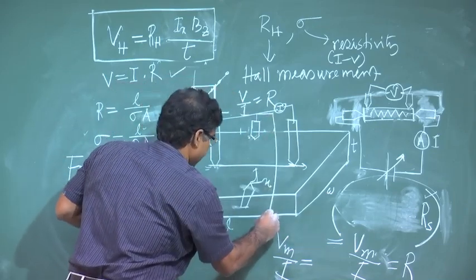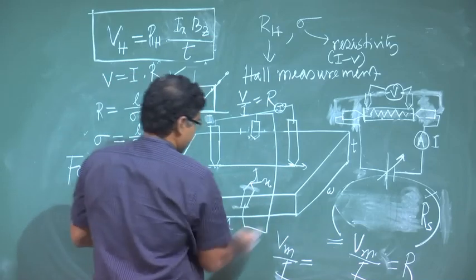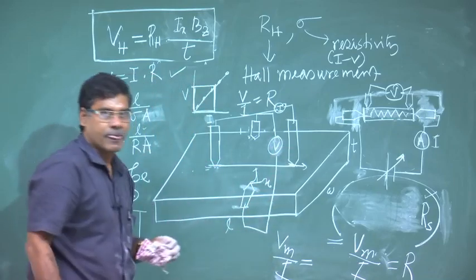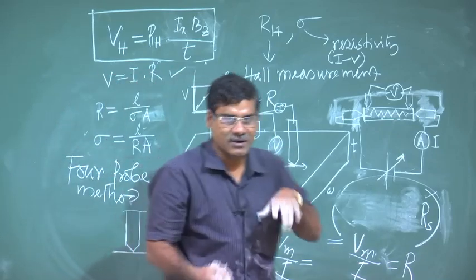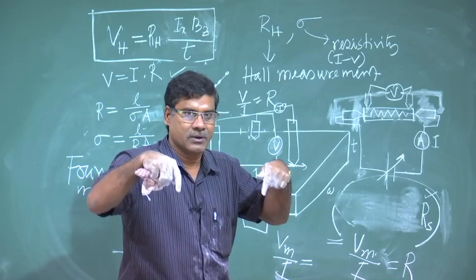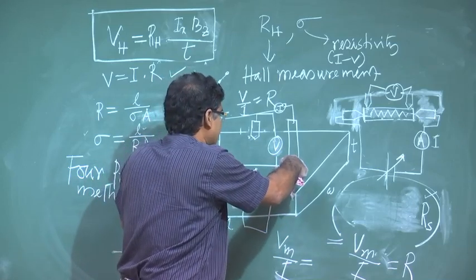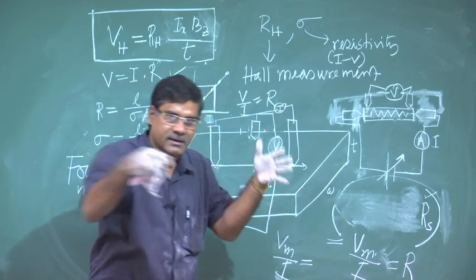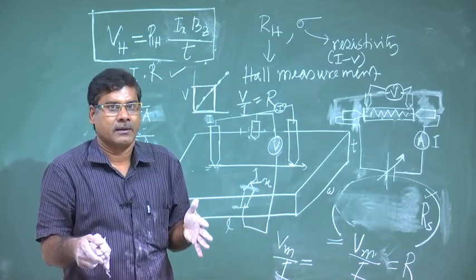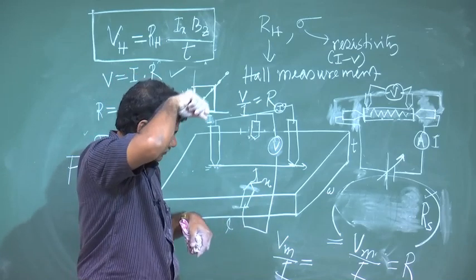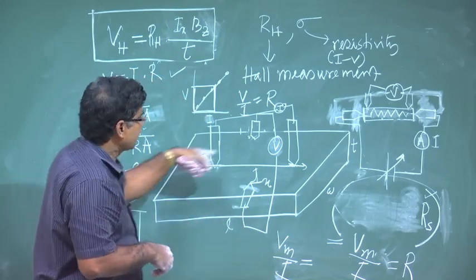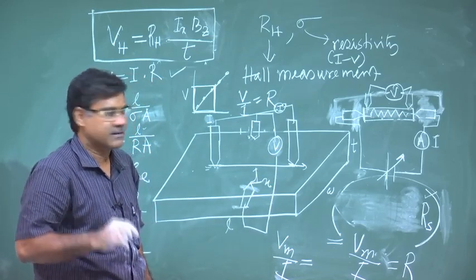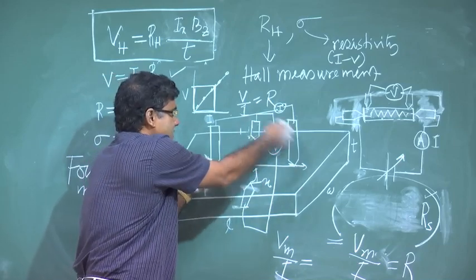These 2 probes we use for measuring Hall voltage. Okay. So, this is now not linear. So, 2 we are using along the x direction and 2 we are using along the y direction, and now this whole sample is put in a magnetic field. Okay. The geometry is called Van der Pauw geometry. So, I will not discuss that part, but this is the arrangement.